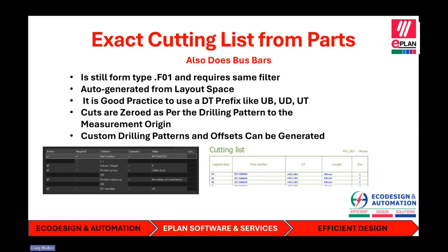But from there, actually moving forward into what is beautifully created by ProPanel, you're able to drop in your DIN rails and duct rails as actual parts. And when you create a cutting list, it knows that in 3D placement, it is exactly this length as you've got it in your 3D object. It has the exact width and height. It's looking for any conflicts or any overlaps or any way it'll get in the way of doors or hinges or anything else. So it's definitely better to go through the ProPanel avenue for this. It'll do bus bars as well and give you all your bus bar lengths so you can pre-cut your bus bars, as well as part numbers and generate reports.